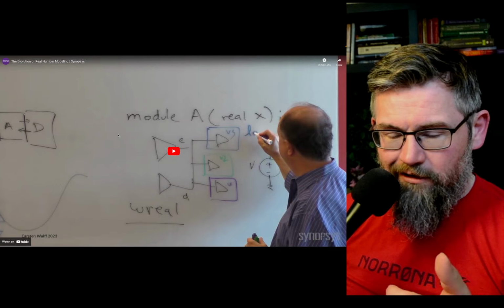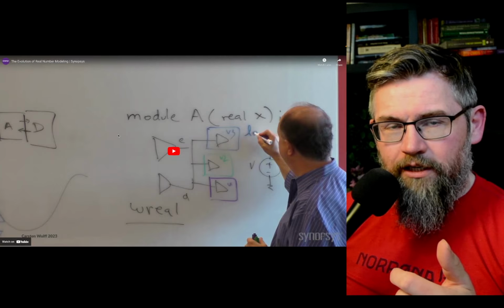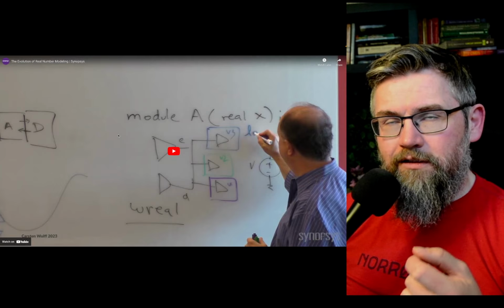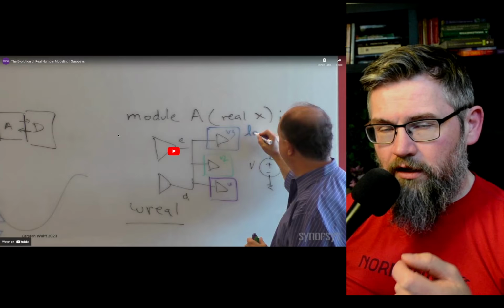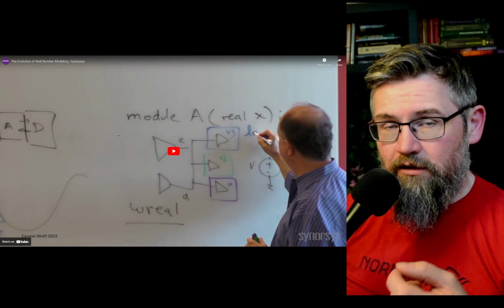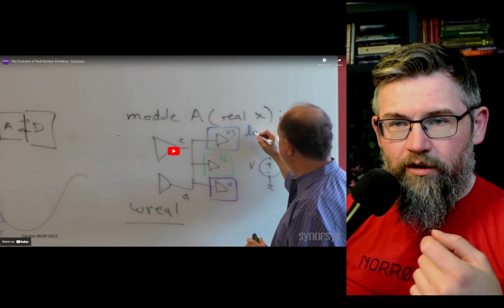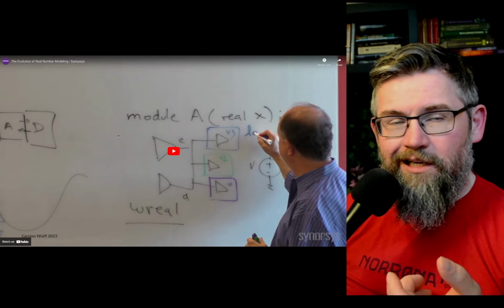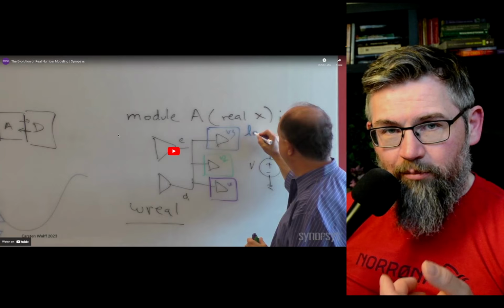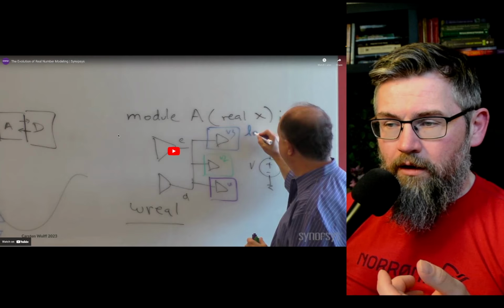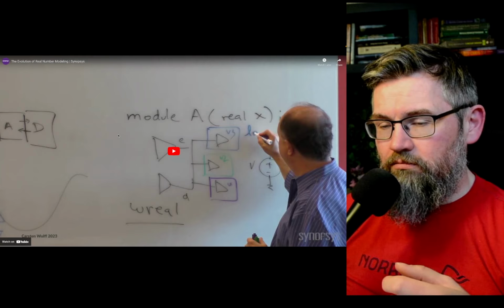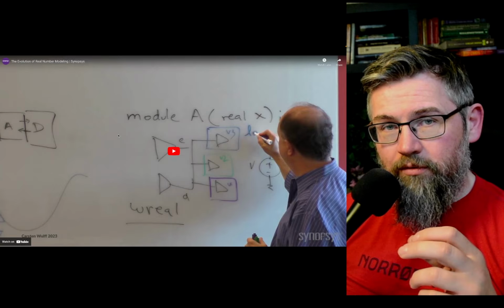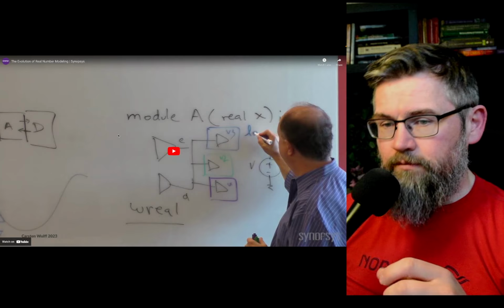So if you like programming and you like analog, then this is quite interesting, because we do this because of simulation speeds. You can't run transient simulation on the top level of a full system on chip today. It's just too complex. You can do that for simple things like a power management chip, but for a microcontroller with a Bluetooth radio and other types of radios, or any really complex system with millions of gates and tens of analog IPs, you simply can't do it. And it might not be possible in the future either, because computers are not getting that much faster. So it is a necessary step to make digital models of analog systems.